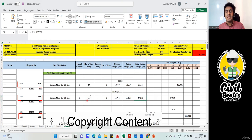I'm referring to a 16 diameter bar. So under the 16 diameter bar, I'll write 23.948 multiplied by the weight of a 16, which is 1.58, which will give me 33.838. Okay, great, fine. So I've got the bottom 20 dia and 16 dia.